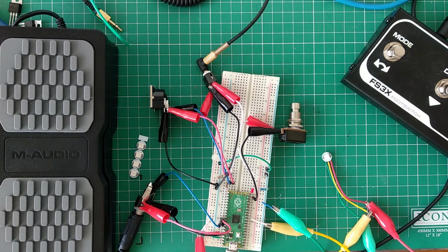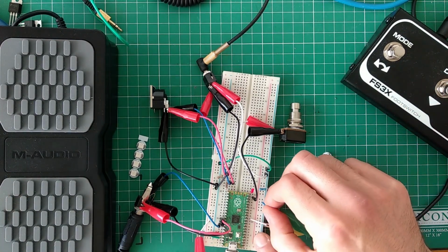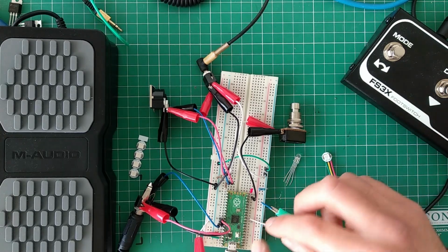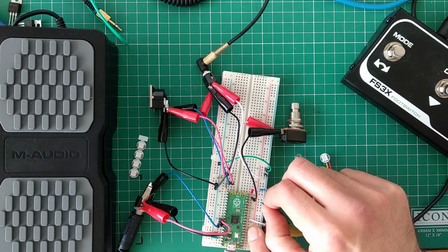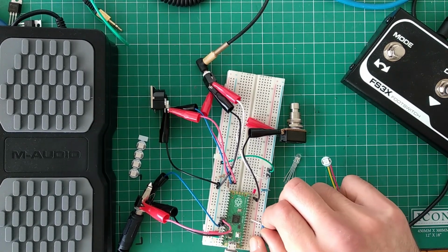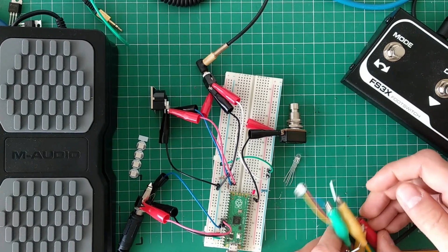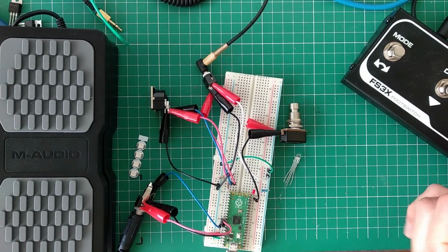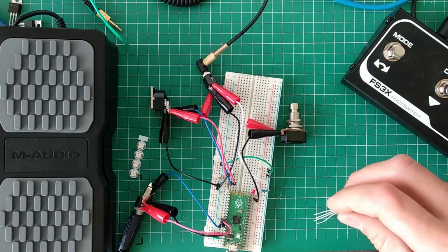When it comes to using your RGB LED, and I have it somewhere here. Yeah, I have it here. So let me just remove my Neopixel. You saw there, it's using 3 wires and 2 are power, and we only use 1 GPIO of our microcontroller. But if you want to use RGB, we actually need a bit more GPIOs, and that might be a problem.